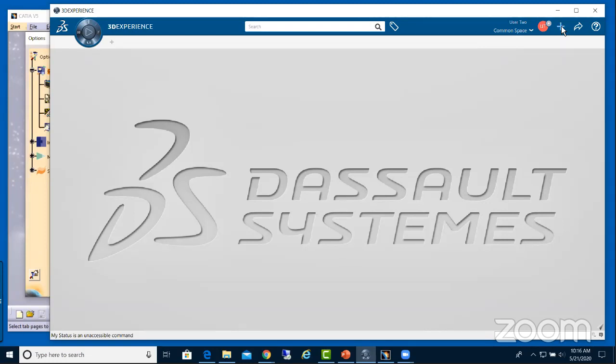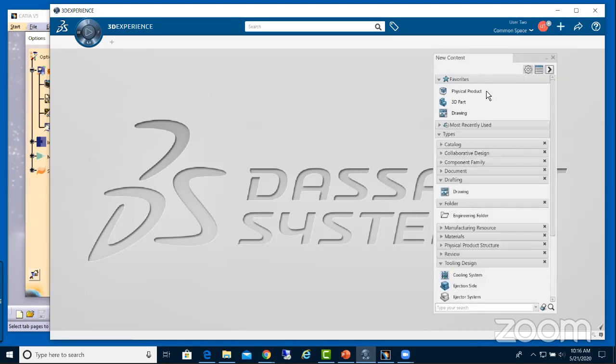Next, we have an important one, which is add. The add service is basically just a plus sign. When I select on it, you'll see that I have content at the top. That creates a document from a dialog box of favorites and types. I'll select on it and show you that here's your new content. So I can actually go right to a document or a part or something that I want to create brand new by selecting on that, or under types, tooling design or anything else. It'll direct me to that new document and open it up immediately.